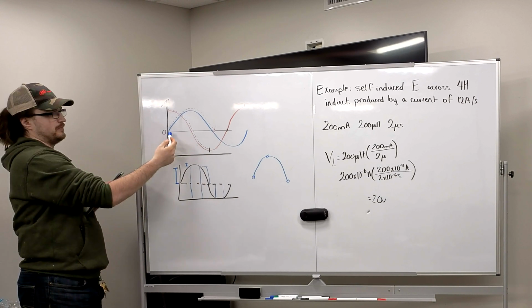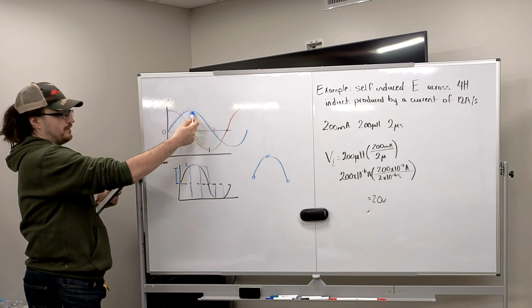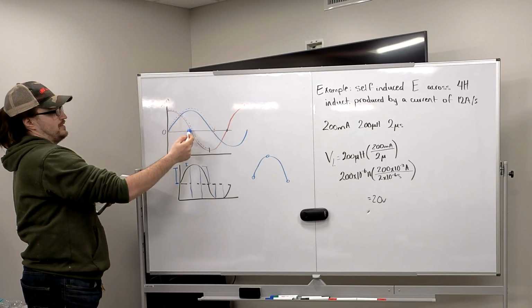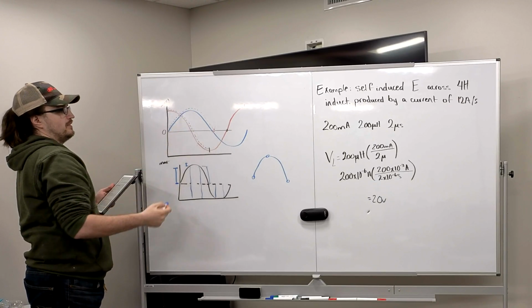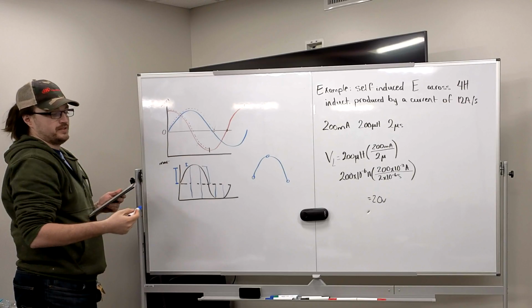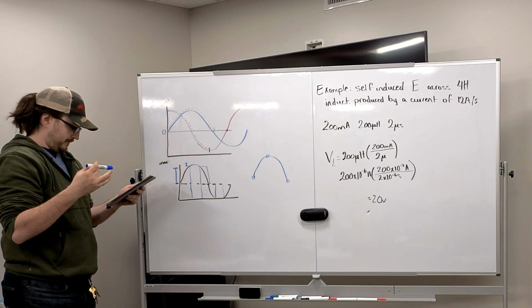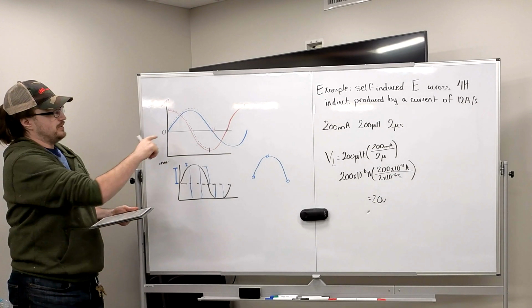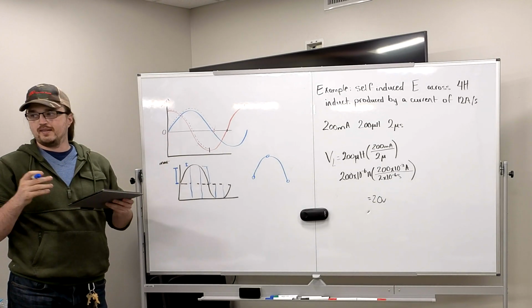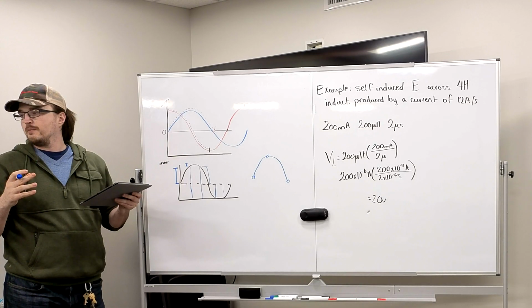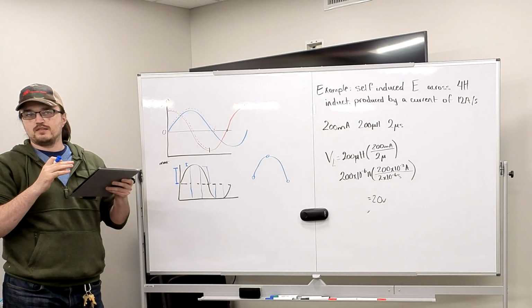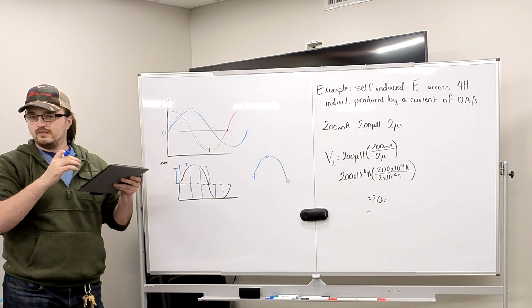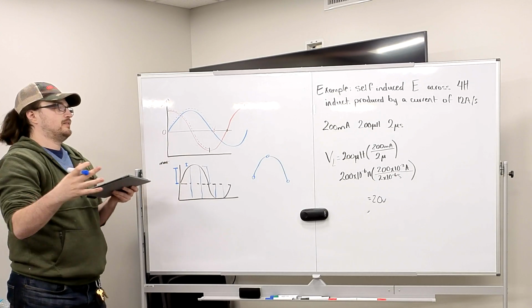During that time, the amperage is increasing, and it maxes out at the same time that the voltage hits zero. Now, at 90 degrees, that means the magnetic field, during this part, was expanding. So it was crossing the other conductors in one direction.